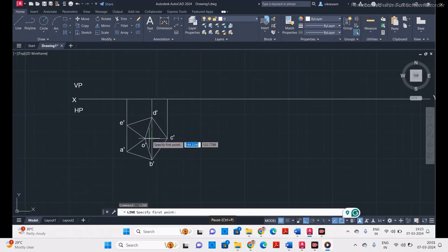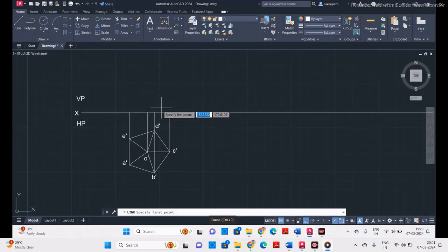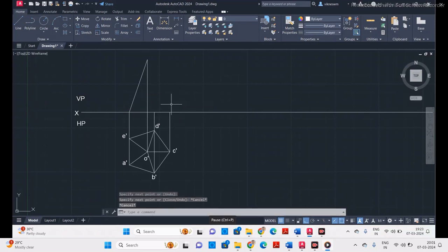Whenever you are dealing with a pyramid, you have to project one line from the center of the given object. Now from the center line, you mark the axis length, which is 60 mm, and then from all the projected lines, you connect to this common point at the top, which is called the apex.